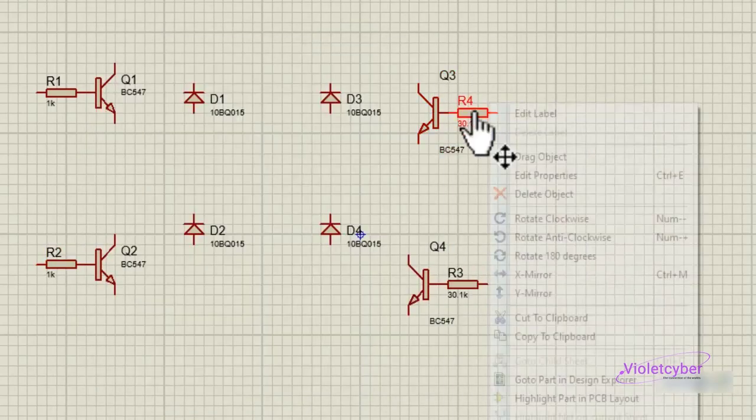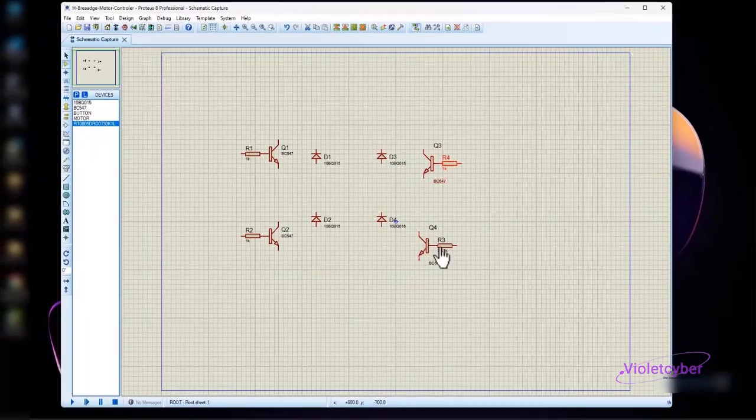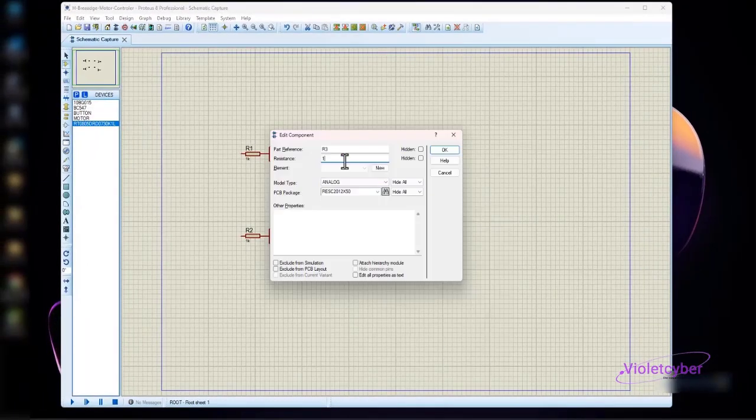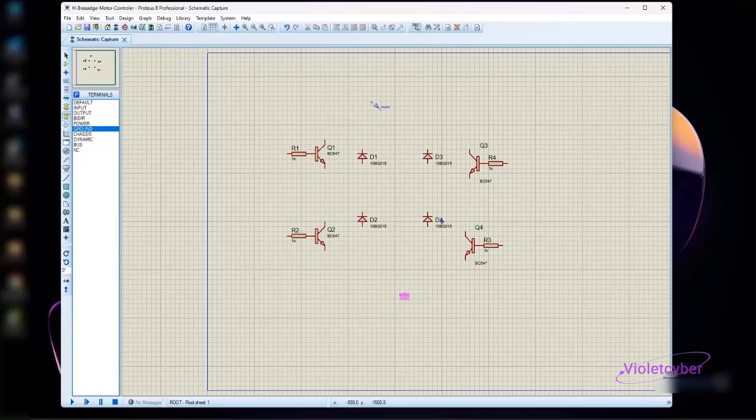The circuit layout in Proteus is kind of like the Proteus tutorial. This one and this one should be the same here. So now our resistors are 1k ohms. Then we'll do the same connection here and done. We'll select the type of source. I'll select DC. Here, this is DC power. And here, I'll select the ground. After doing this, I'll now do the wiring.